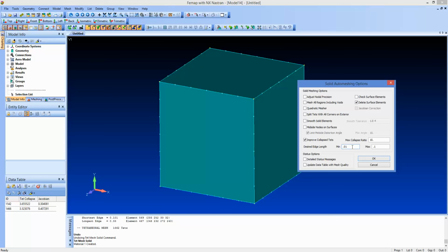Now, if you look at the actual help file, which you'll look at in a second as well, you'll see that it says it will follow your desired minimum and maximums as the geometry allows. So it's kind of nebulous. In fact, I happen to know if I set these and run it, it's going to ignore them anyway. It's going to make it bigger than the maximum.